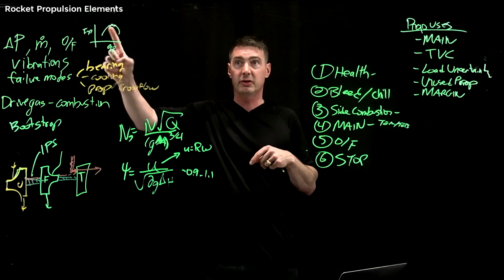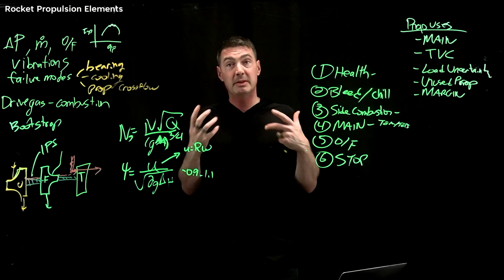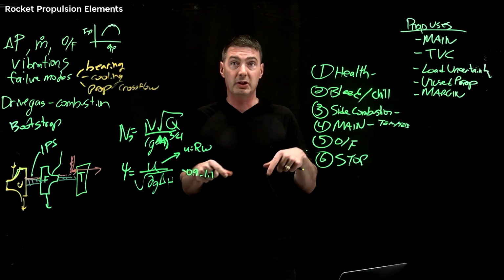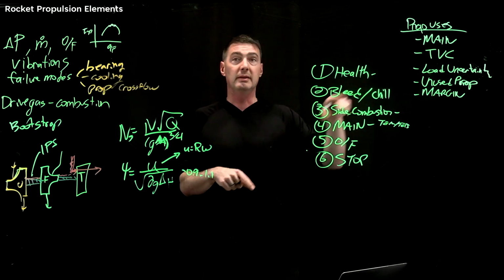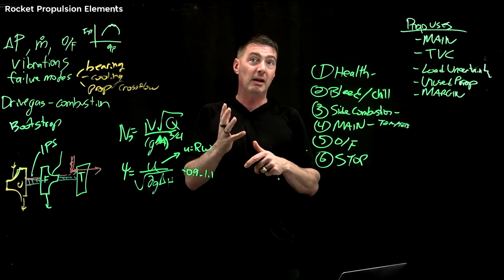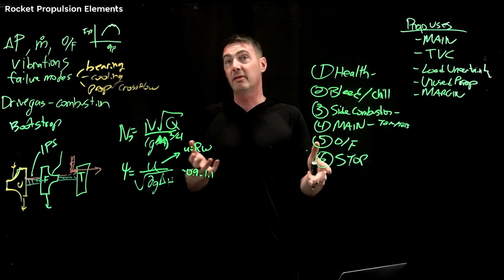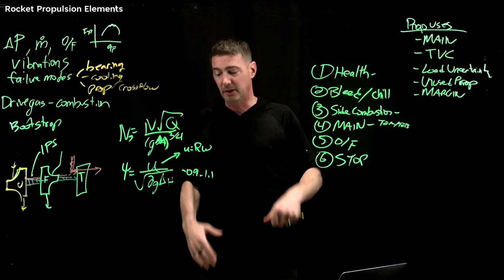Again, making sure you hit all those optimal conditions. And then you usually have some sort of acceptance test that you're going to do. Maybe it's full mission duration. Maybe you're going to swing all your TVCs. And so usually that might eat up about 10 starts of the engine. And so having a process that is not destructive is actually critical, even if it's an expendable vehicle.